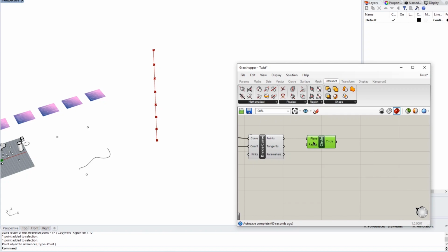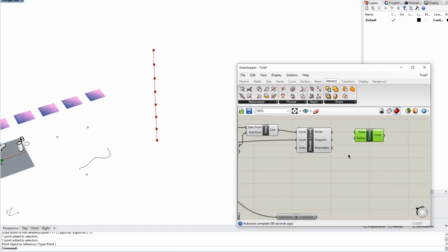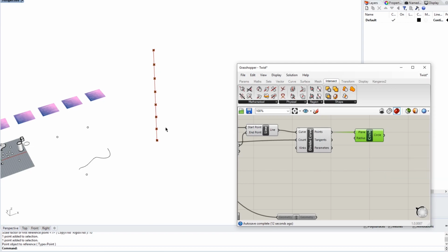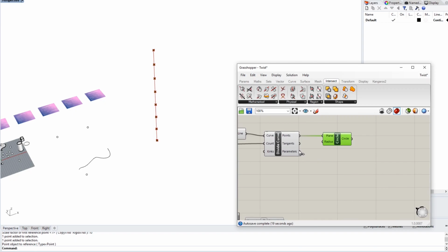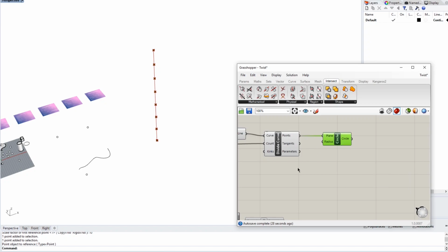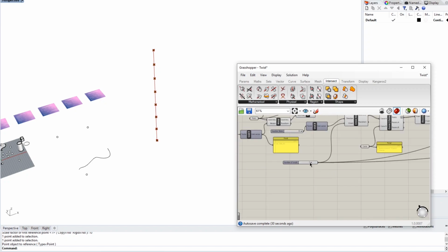Radius, this is what we need to input, and we would like to input a list of values for that. If you also pass the points into plane, it automatically assumes all the points are the origin of the circle, with the XY plane. So for the radius, corresponding to the list of, in this case, 8 points, because we have placed 8 as the number of levels.